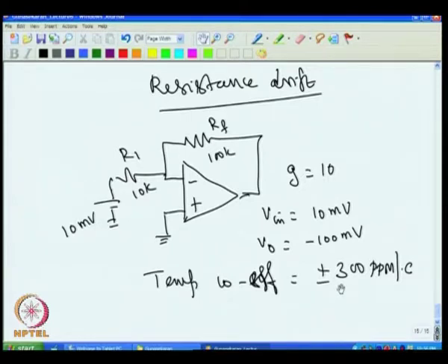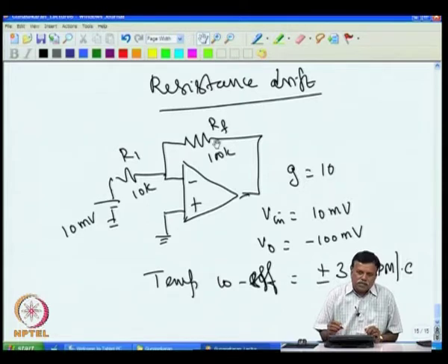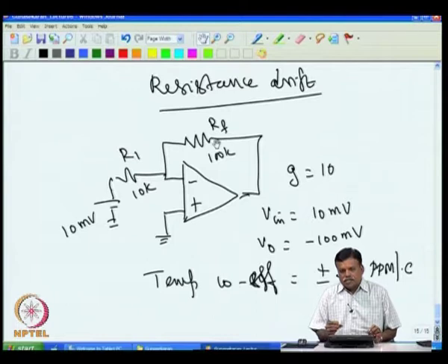Normally we think that if I take a wire, that will always have a positive temperature coefficient, but when you make it a wire wound resistor, you will not get a temperature coefficient as plus alone, because the characteristics of the entire resistor property change when you make it as a pellet, or a wire wound resistor, or a metal film resistor. Then the property of the resistor is totally different from the pure metal property. So, one should not think that resistance will always increase only, or that all 100Ks will increase. That is not true.